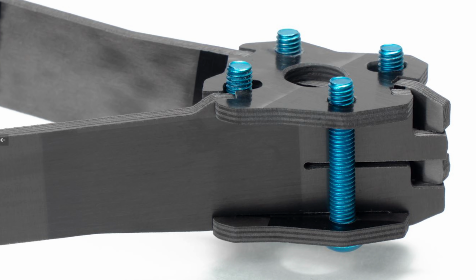It's just vibrating to the rotation of the motors and props. And it's just so interesting that you say that, because those are the designs that I'm working on right now. I'm looking for a design that's stiffer, that has a higher frequency of resonance, so that it's well above the range of rotation of the props. Exactly. That is what. I don't know if that makes a significant difference in tuning.